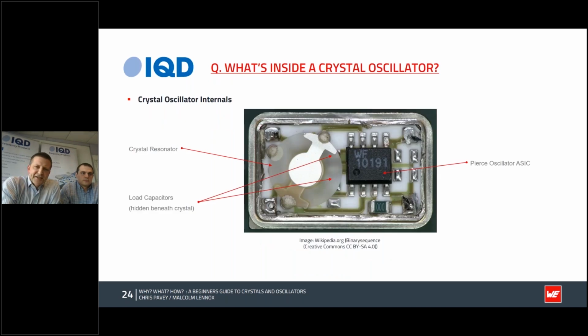So an oscillator has a circuit built in to generate a set frequency. What is included in this package? An oscillator is an integrated circuit, or IC, that has a crystal resonator, a Pierce oscillator circuit, and an output stage built in. All you have to do is apply a voltage and you will get the correct output frequency. Oscillators come in many different varieties and offer many stability specifications or control options by using different technologies.